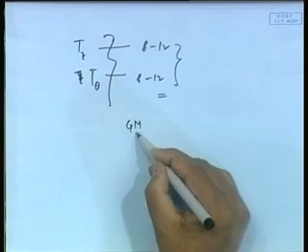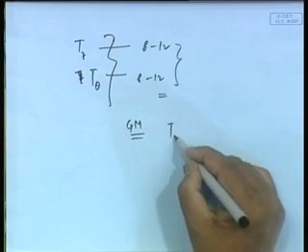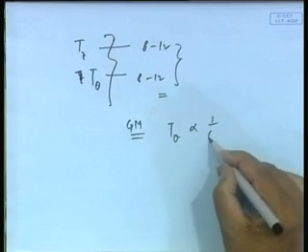And one of the things that we could do, we will see in roll motion later on, that an interesting inverse case occurs. You actually might have to raise center of gravity to lower metacentric height, because you see if GM, say in offshore structure, we have seen that periods are proportional to 1 by root GM.